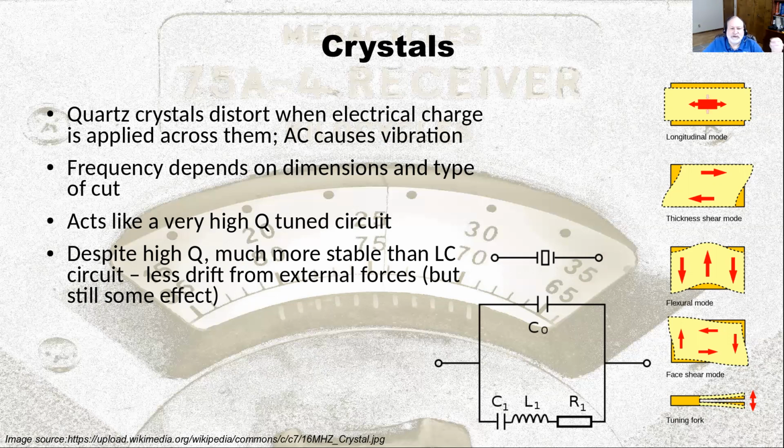However, another really good factor is that despite it being high Q and despite what I just said a minute ago, it's much more stable in frequency than an LC circuit. There's less drift from external forces, although still some. And that's because the quartz material is less impacted by temperature changes than other materials. Also, the quartz is smaller, it's mechanically solid, and for various reasons, it is dramatically more stable in maintaining its frequency than an LC circuit. So it becomes the ideal thing to use as a resonator, particularly in oscillators.